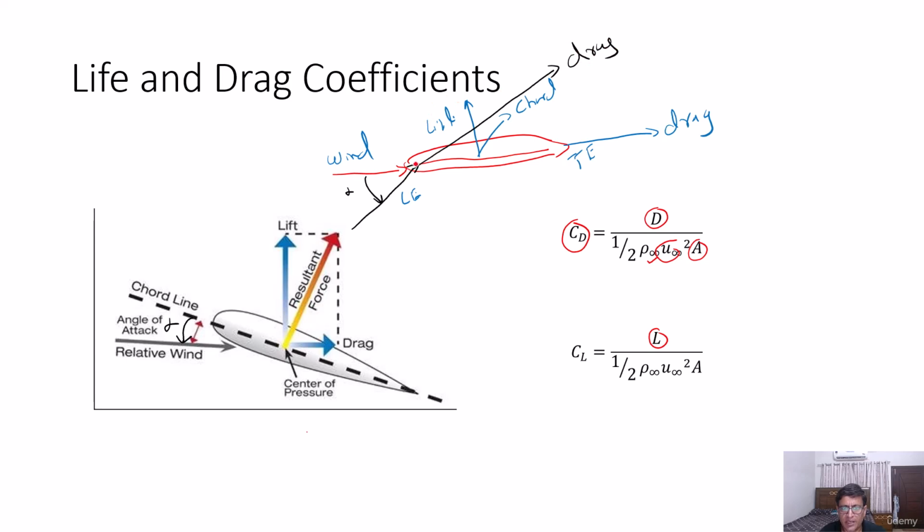Okay, and the lift will be tilted by the same angle, 90 degrees, but this lift will be here. So now what we are doing in CFD Post is that if the angle of attack is 10 degrees, which is here, and the same angle which the drag is making with the x-axis, we are just rotating our coordinate frame by 10 degrees, so that we evaluate on these new axes, because we are not putting any angle of attack in CFD Post, it is not possible.